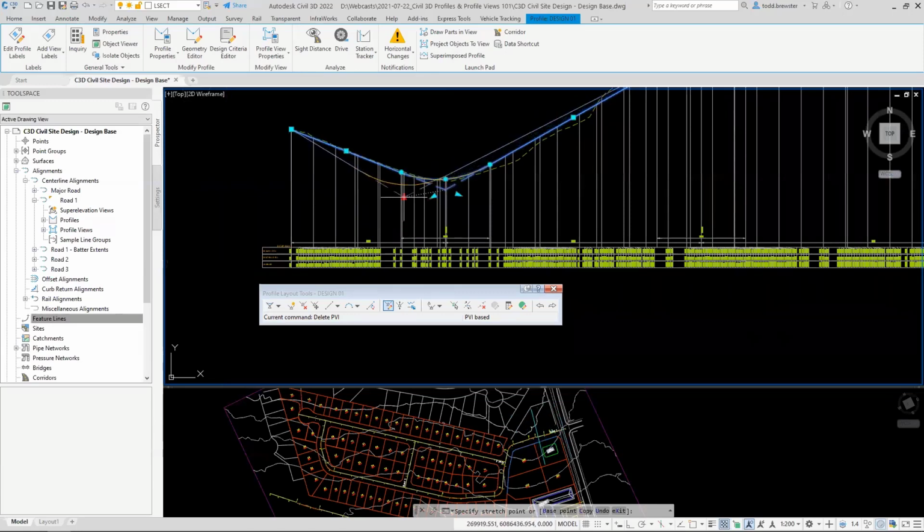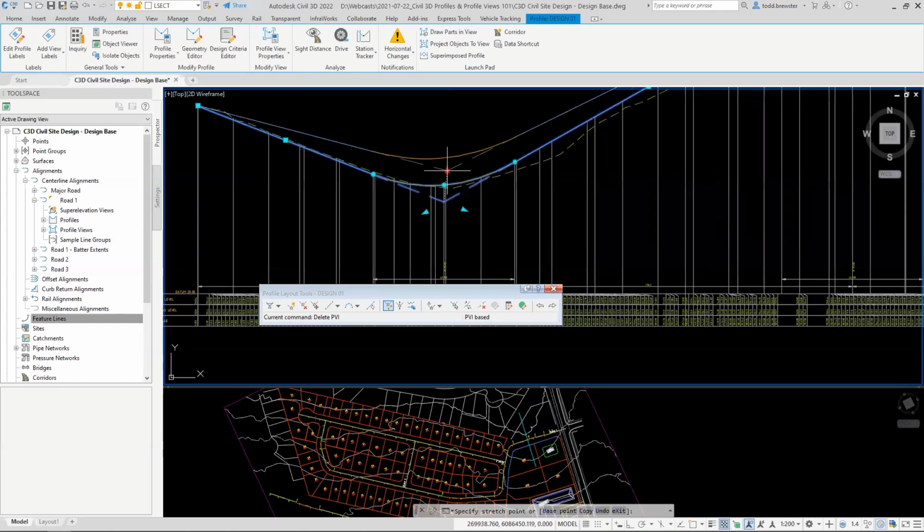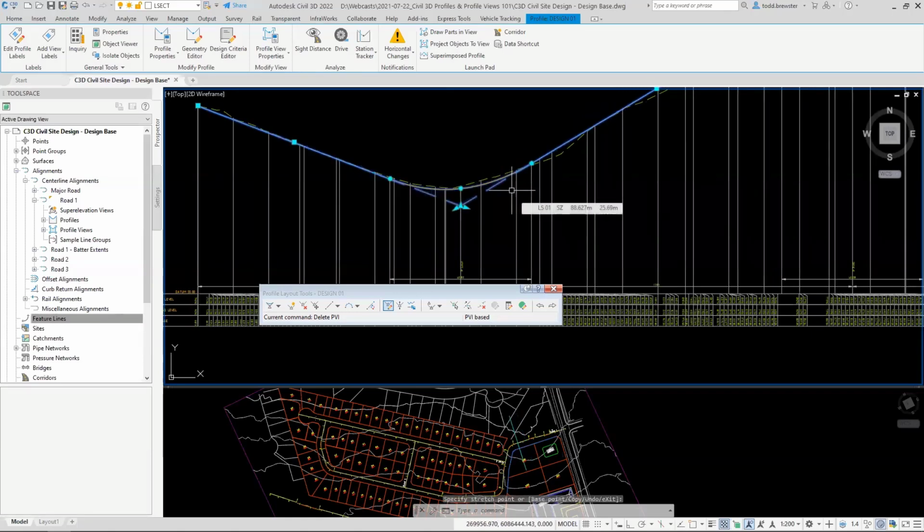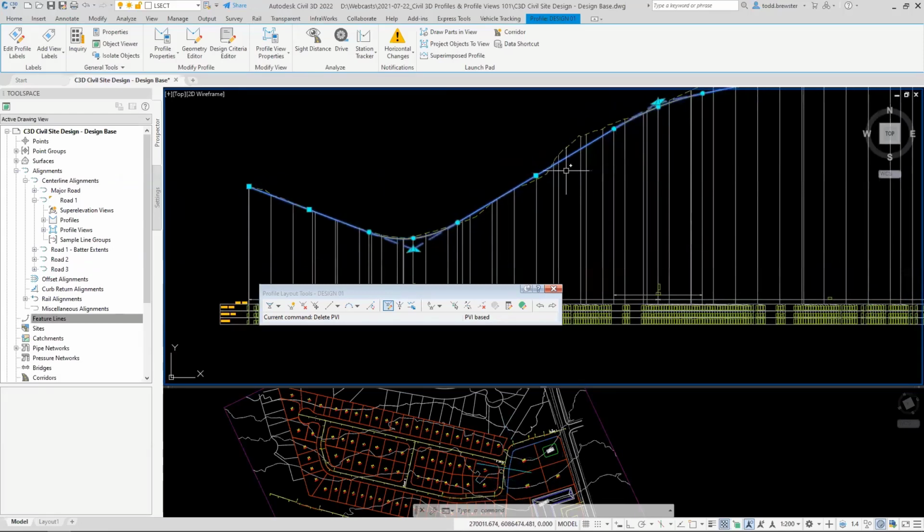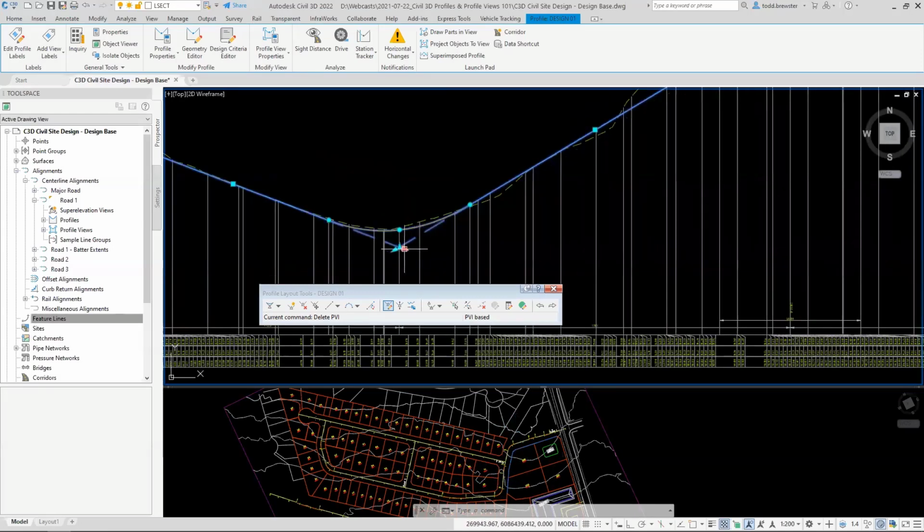And then when I do something it can't cope with, it just doesn't give me a preview because it's not possible. So I could come in here and attempt to fit this to my existing grade. So maybe there. So it's just left click to drop things. And then if I want to perhaps fit this position in a little nicer, I could grab this IP here and constrain the grade to match to that, and then go, yeah, okay, that's a better position for that.